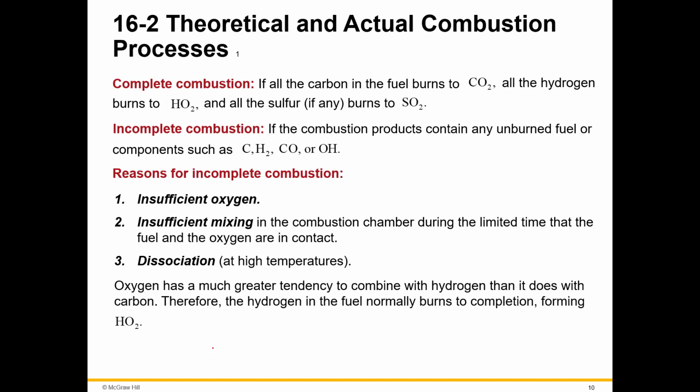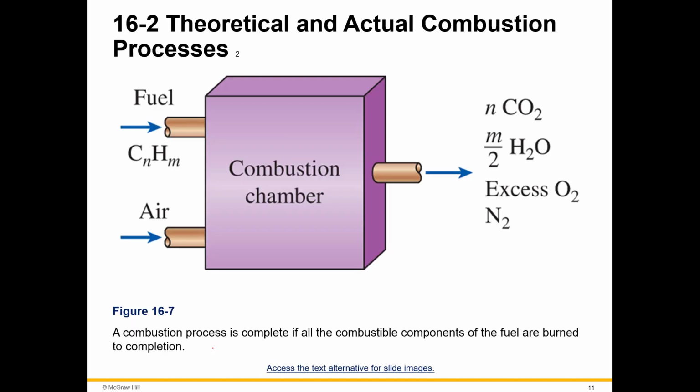What are some of the reasons for incomplete combustion? Well, it goes back to those ratios: insufficient oxygen, insufficient mixing, and dissociation, which is high temperatures. Oxygen has a much greater tendency to combine with hydrogen than it does with carbon. Therefore, the hydrogen in the fuel normally burns to completion, forming H2O.